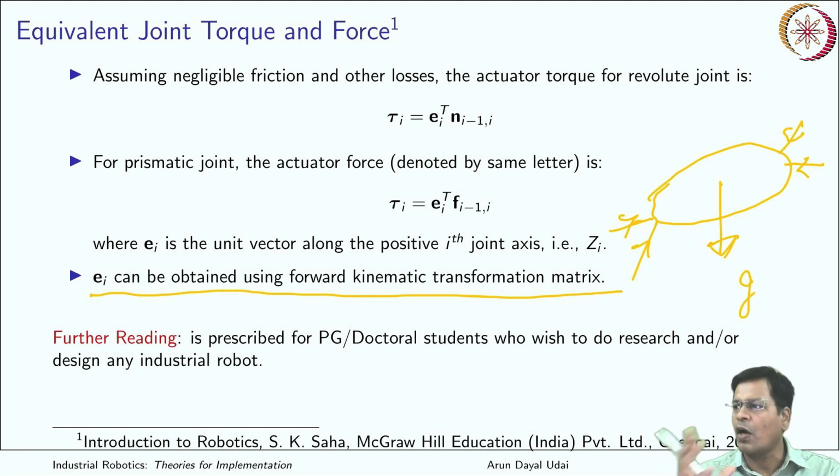Now you can analyze your solid body, which is your link, using all sorts of forces that come on it. At least the static forces, you can design this link using them. Taking a factor of safety, it should be good enough if your robot does a quasi-static job, if it is moving very slowly or is static.